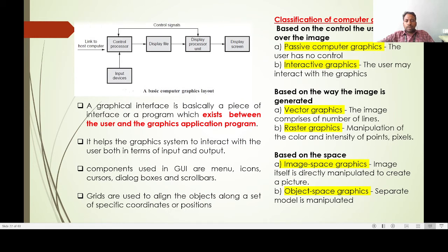Sketching is used to draw lines, arcs, polylines and various other objects. For sketching, we need to give a command to draw. If you want to draw a line, give the line command, then give the starting point and end point. A line is a connection of 2 points: a starting point and an ending point.